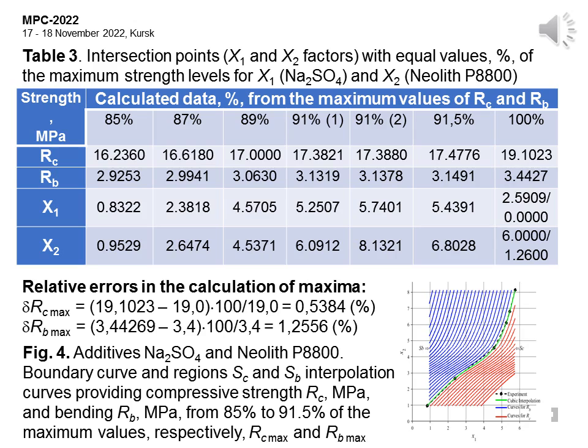The concentration of modifying additives has been revealed, which makes it possible to achieve the required properties of the composite, guaranteeing a decrease in strength by no more than 9.5 to 15% of the initial values. The indicated concentrations were sodium sulfate from 0.83 to 5.43 parts by weight of cement, and redispersible powder from 0.95 to 6.80 parts by weight of cement. The developed scheme allowed us to determine the optimization criteria for any number of modifying additives and the level of required qualities of compressive and bending strengths.